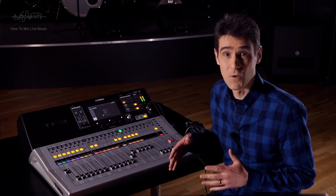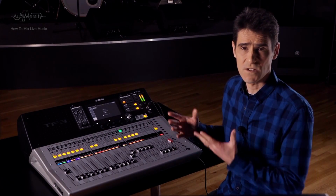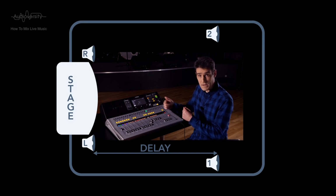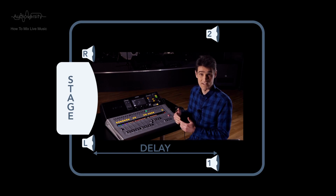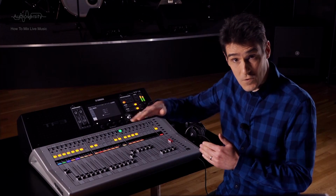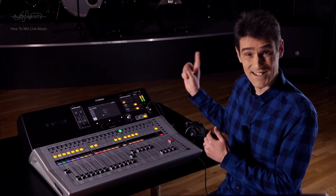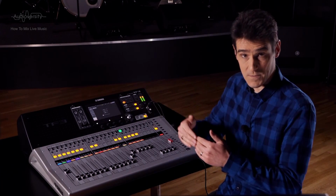Imagine that from some seats in the audience, you can hear some sound from the PA speakers, but it's not loud enough. So you add some speakers closer to these seats. Now the people in these seats can hear the sound from 2 sources, the near speaker and the far speaker. But the sound from the near speaker reaches them first, because the sound signal travels through a wire much faster than it does through air. This can create an unpleasant sound for the listener and it draws more attention to the nearby speaker than the stage. To compensate, add delay to the sound for the near speaker.